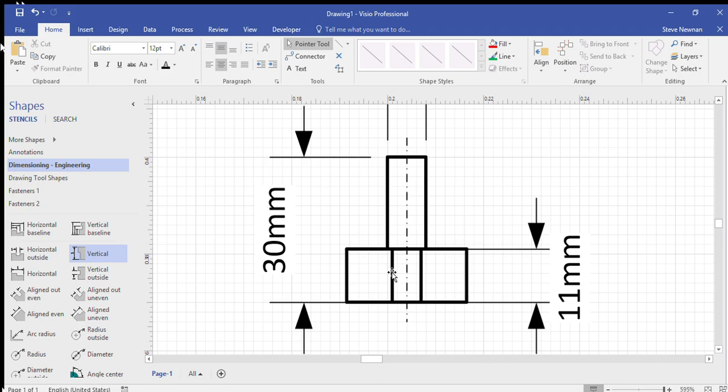So if they're hidden, we should go click, line, dashed, dot. If a line's dotted, it means it's hidden. So even though we know there's something there, we can't really see it in the drawing. And we should probably change those to be a bit finer as well. Weight, half, line, weight, half. Alright, so we've got that so far.